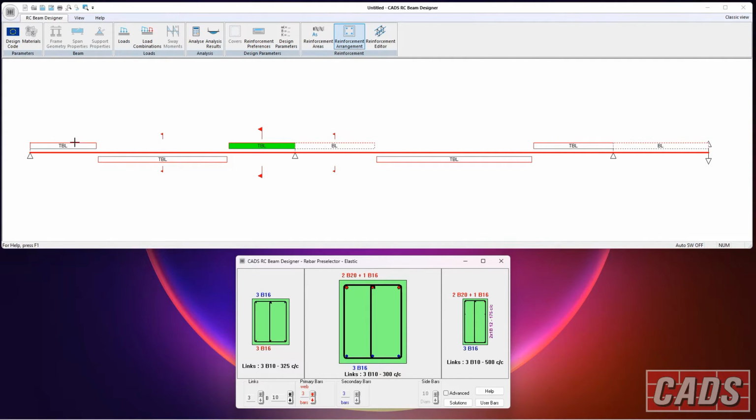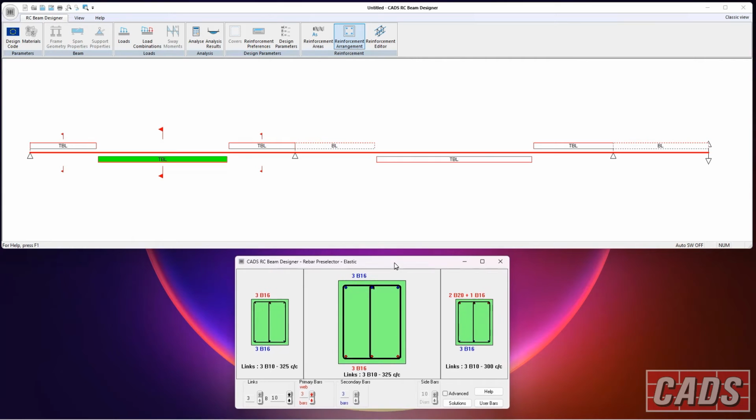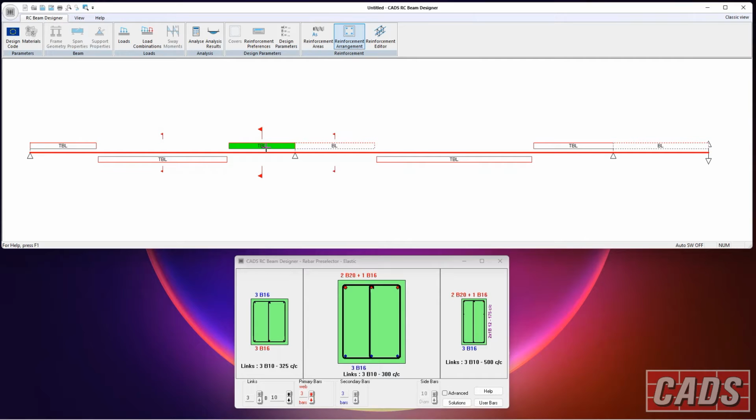It's giving us the 3 design zones here, here and here. Now the detail you're looking at in this section below is the detail at this point here in green, and then the associative detail to the left and right of that. Now the T, B and L means the top, bottom and link bars can be edited.